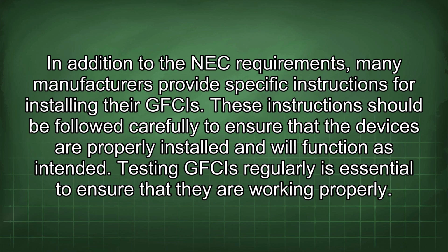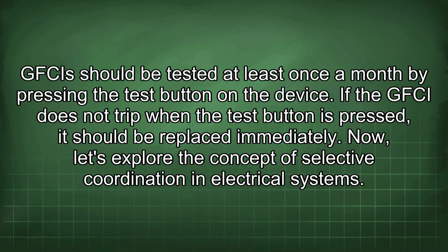Testing GFCIs regularly is essential to ensure that they are working properly. GFCIs should be tested at least once a month by pressing the test button on the device. If the GFCI does not trip when the test button is pressed, it should be replaced immediately.